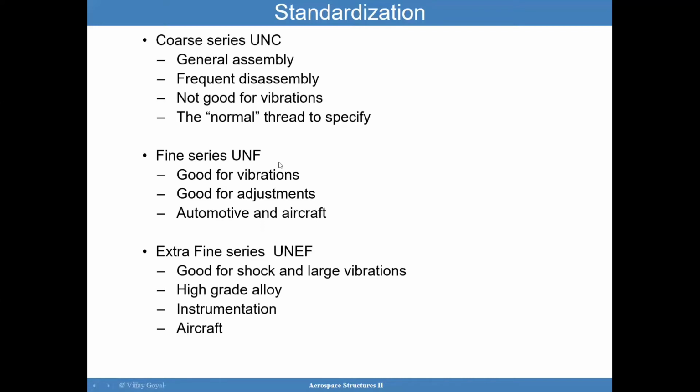The UNF is used quite a bit in the automotive and aircraft industry. The extra fine series UNEF are good for shock and harsh vibrations. They tend to be high grade alloy, and they're used in aircraft.